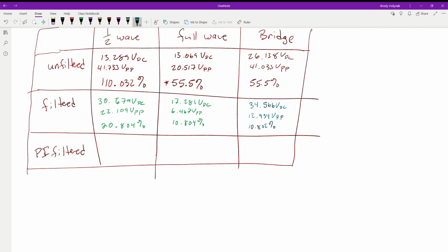When we build these, it's not unusual to see 20, 25 watt resistors for your shunt resistor because there's so much voltage being dropped. So again, that comes into your designs. Do you want a big old honking heat sink with a resistor on there, or do you want something smaller that fits in nicer, looks better, stays cooler? When you're designing these, you have to take those into account.